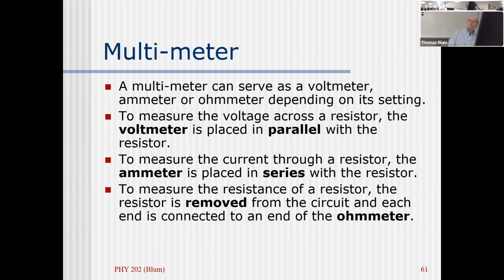If I walk by and start pretending that I'm smelling smoke, that means you've got your meters wrong and you need to fix it. There won't be any actual smoke smell, but I'll pretend. Ammeters measure the current. Things in series see the same current. So if you want to measure current, you put your ammeter in series, because things in series see the same current.